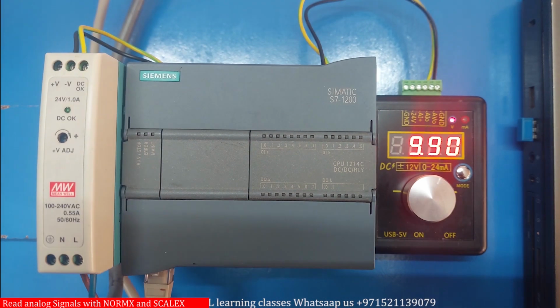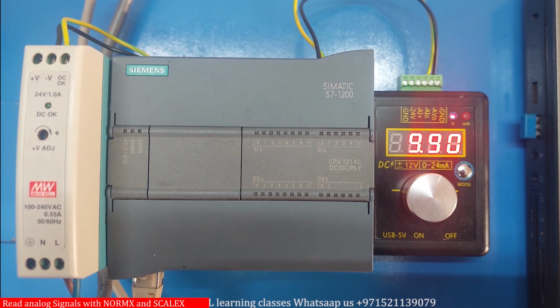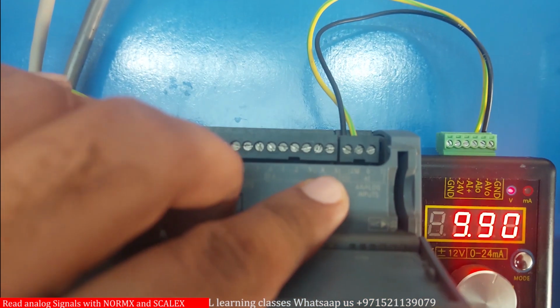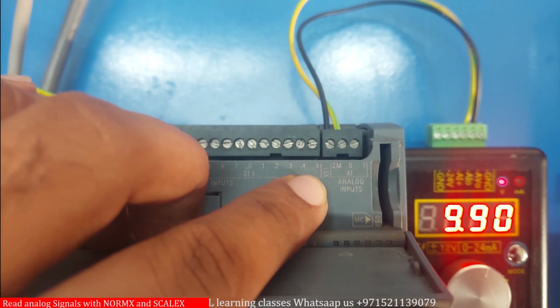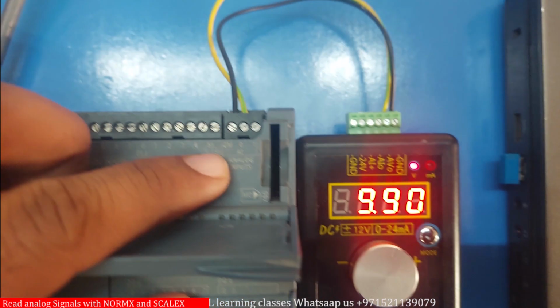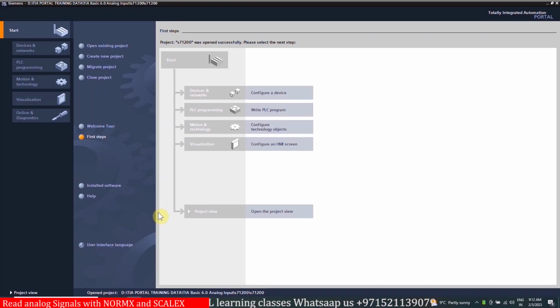As you can see, today we have an S7-1200 PLC and we have connected an analog signal generator with it, and we have connected the 0 to 10 volts analog output of the signal generator to the analog input channel 0 of the S7-1200 PLC. Now let's go to the TIA portal software and see how we can make a program to read that analog signal and how we can scale the signal into some usable values.